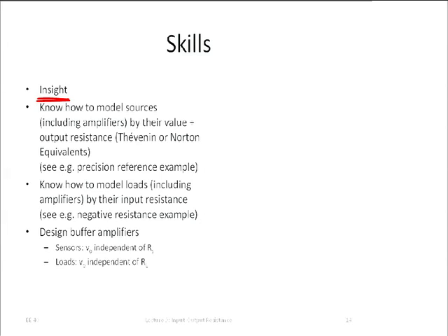there was also this kind of thing of a buffer amplifier. We found that sometimes we need an amplifier not in order to get voltage gain, but such that we don't pull so much current from the source. Because if we use a non-inverting amplifier, for example, then we can observe the signal without consuming any current if the amplifier is ideal.